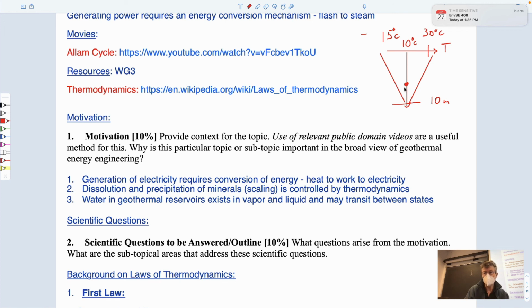So we're interested either in the geothermal fluids themselves, or using those geothermal fluids to influence phase changes in other fluids. A binary plant system for a big geothermal project, or a ground-sourced heat pump, they work on exactly the same principle, except a ground source heat pump, I guess, doesn't generate electricity. It uses the phase change to suck heat out of the water that comes in at only 10 degrees centigrade. That's it.